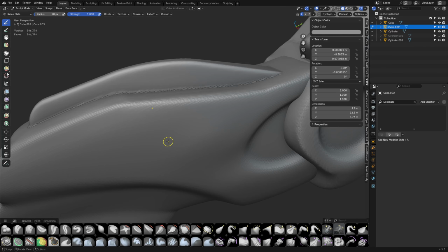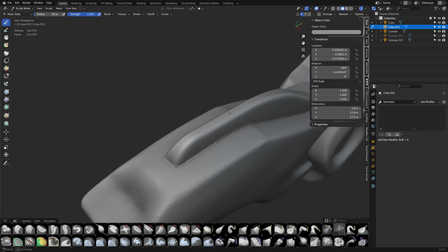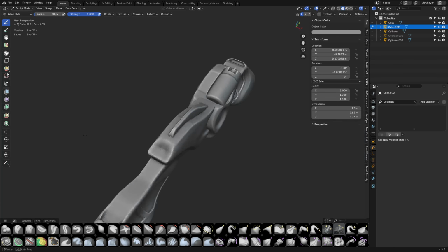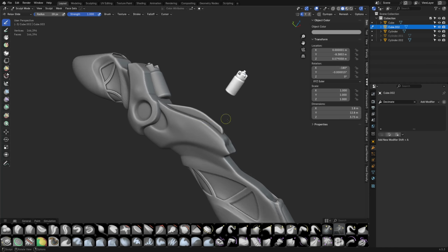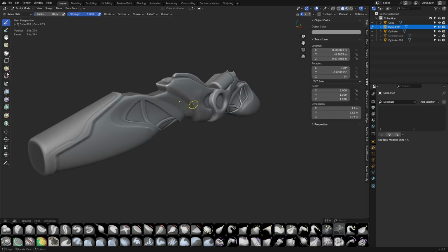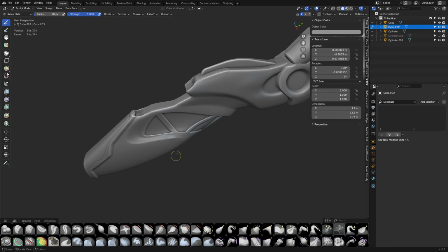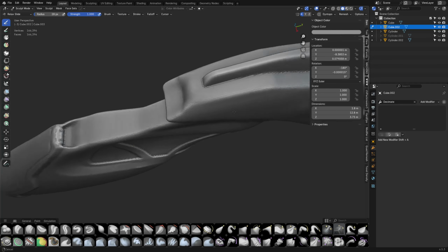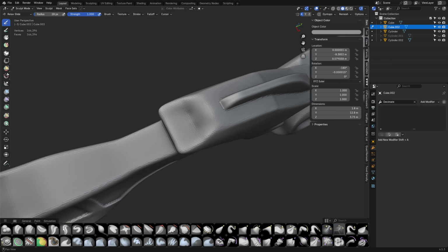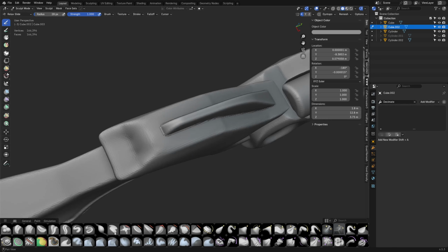Blender needs something like the voxel remesher, anyways. It should fluctuate, I think, in my opinion, up and down every time you hit Control R, so that it avoids that situation. If the Blender devs would start doing that, I think that would be amazing, because otherwise you get those little dots everywhere and it could destroy your mesh. It took me a while to figure out what was going on there, but yeah, fluctuating up and down will help you out quite a bit. So we basically now have a good mesh compared to what I said earlier. It didn't really mean anything, but it wasn't true, I guess.